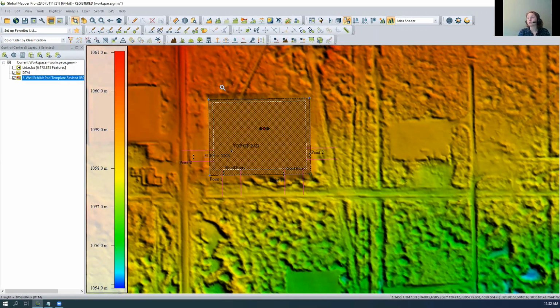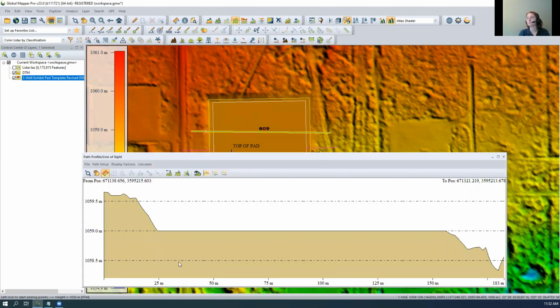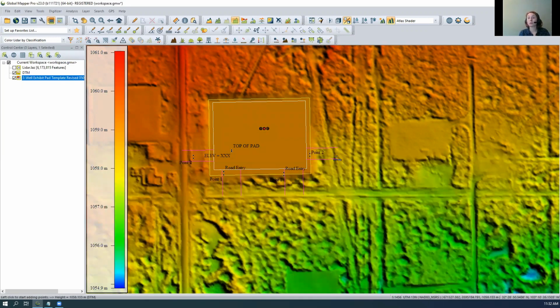Closing the terrain painting tool and clearing my feature selection, we see again this is a flattened area, and we can explore that further in the 3D view or with this cross profile. We have our feathered or sloped edges, our flattened site plan, and a slope on the other side as well. Now we've altered this terrain, we've mocked up this flattened site for our new project, but we don't actually have any numbers associated with this. We didn't get any volume calculation from that terrain painting method.